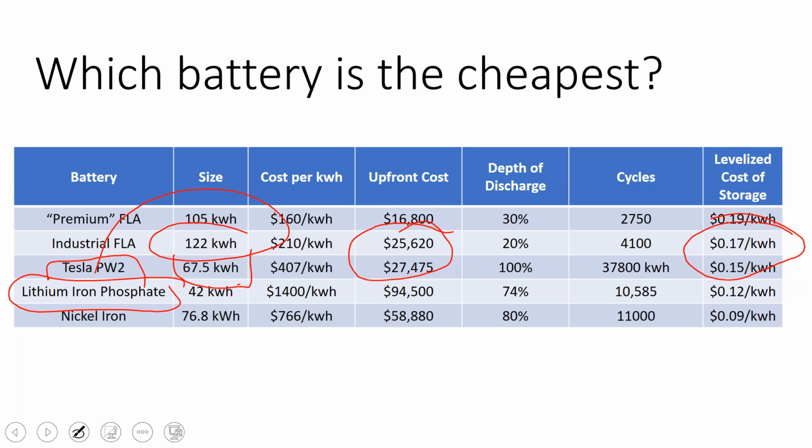And the big difference is if I go with the Tesla Powerwall, it's a more responsive battery and there's no maintenance, but there's also that hard difference of having a 120 kilowatt hour battery versus a 65 kilowatt hour battery. If your goal is to live off grid and never run out of electricity without really thinking about it, having that extra storage, particularly in an industrial forklift battery that could be deeply discharged without wrecking it, sometimes it's a question between maintenance or storage capacity.